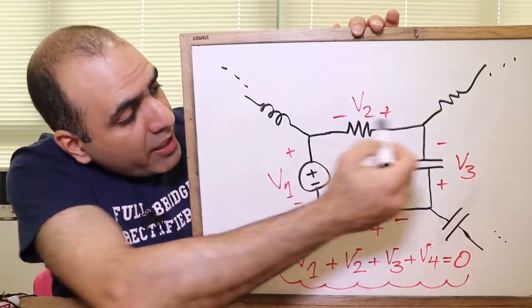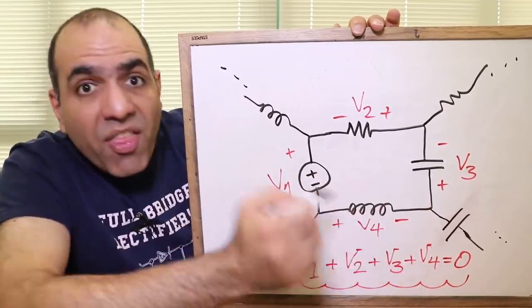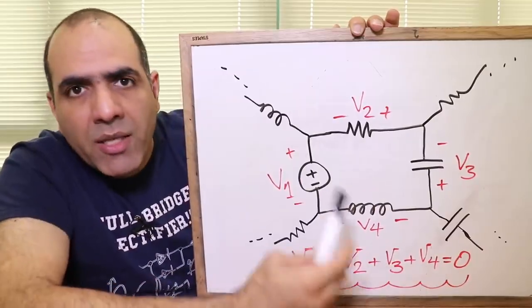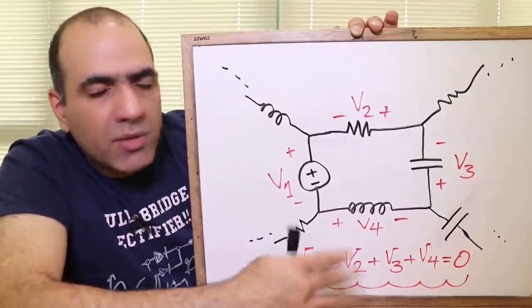Kirchhoff's circuit laws. One is Kirchhoff voltage law, or KVL, and the other one is Kirchhoff current law, or KCL. You need to understand these well, because soon we will be designing circuits together. These laws are easiest to understand and work best when the components are lumped and nothing radiates on nothing else. So let's start from there. Kirchhoff voltage law states that in any closed loop of a circuit, the sum of all voltages across components in that loop is zero, and that's based on the law of conservation of energy. And lumped model makes it easy. I'll talk about that later.